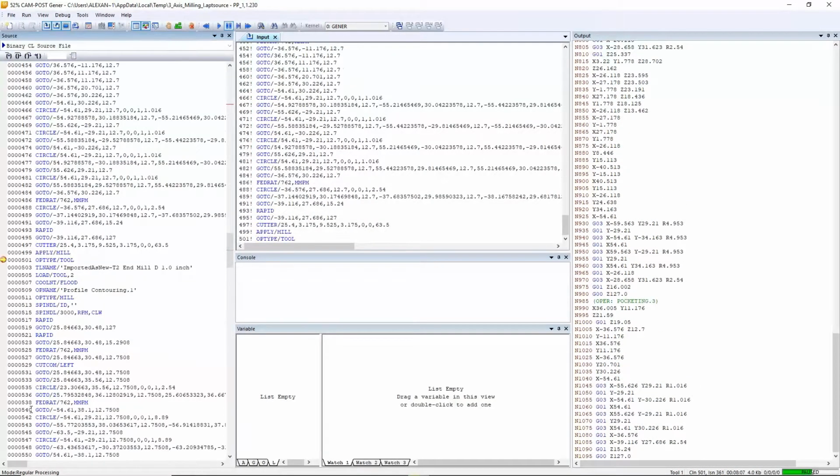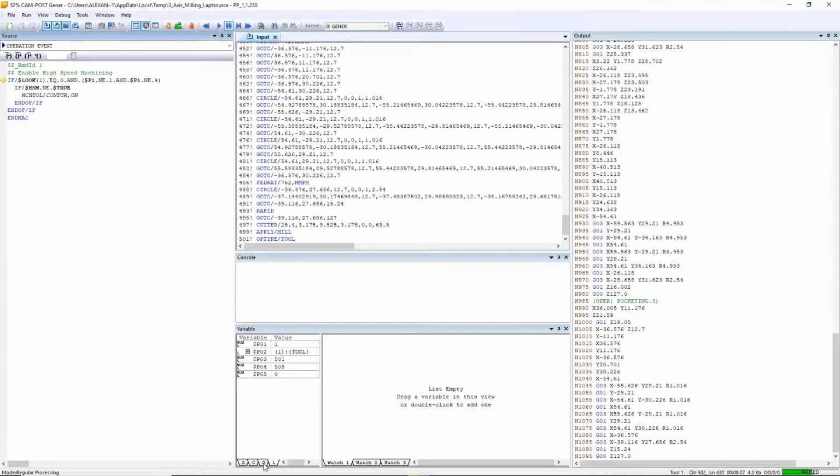The Local tab will keep track of all the local variables used in the post. The variables will appear as the variables get triggered in the macros. Once you get out of the chosen macro, the list will return to empty. Global and object variables behave the same. The difference between a global and object variable is related to CamPost, our complete development platform.